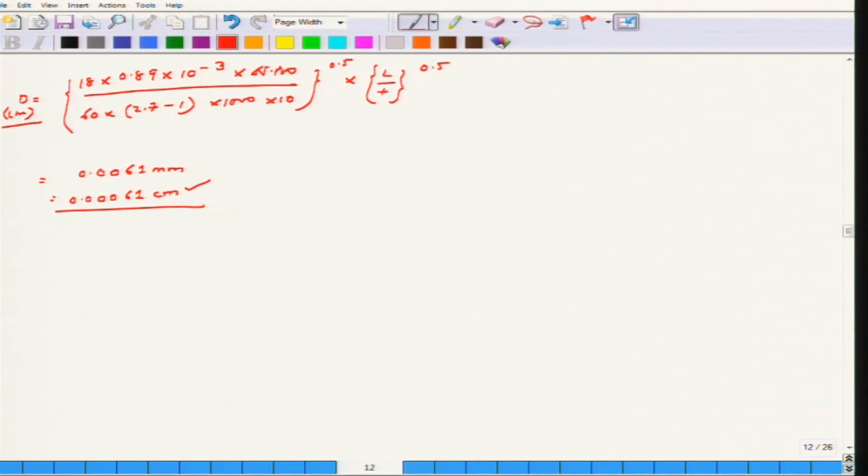When you go through a sieve analysis, a stack of sieves is given to you. Because you know the sieve size opening, you know the equivalent diameter, and what you do is find out a term called percentage finer. That means how much material the sieve has allowed to pass. In this way, here also you are supposed to find out the percentage finer.